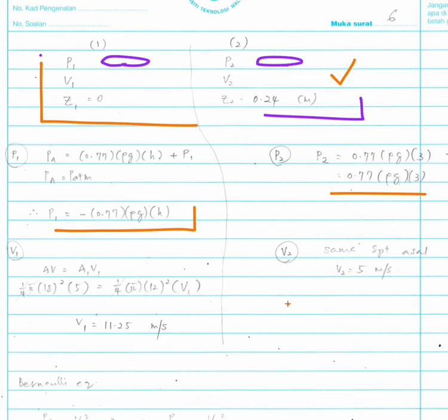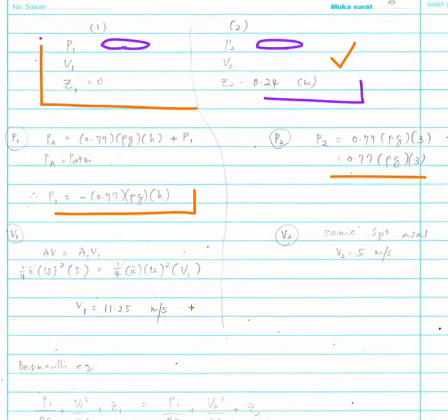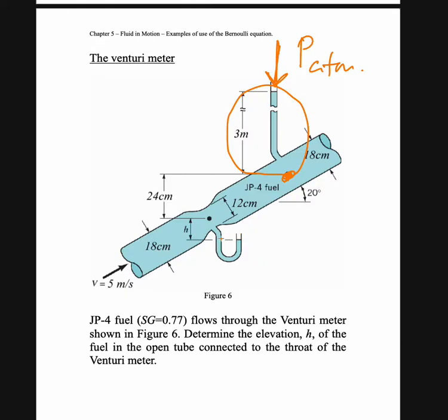And then in this situation, we know that the water flows at 5 meters per second. We know the velocity, we know the diameter, so we could calculate the value of Q, meaning the volume flow rate can be determined. Okay, but now at point number 1 here, we know that the velocity is increased. Why? Because the diameter is smaller compared to the diameter here.